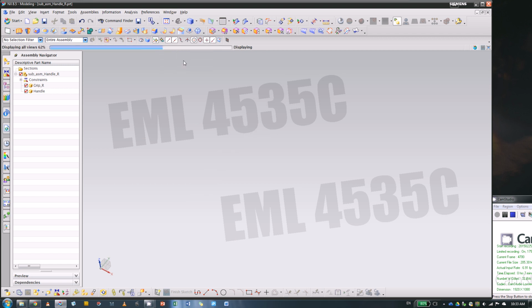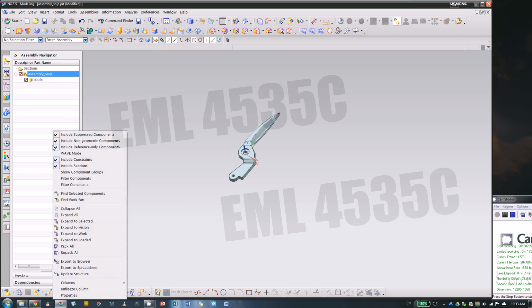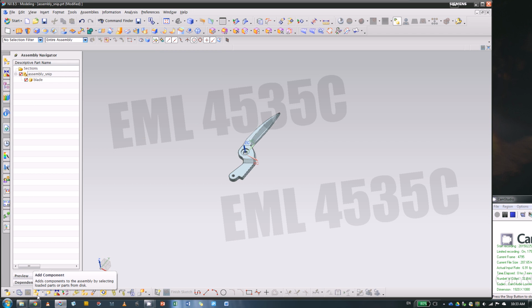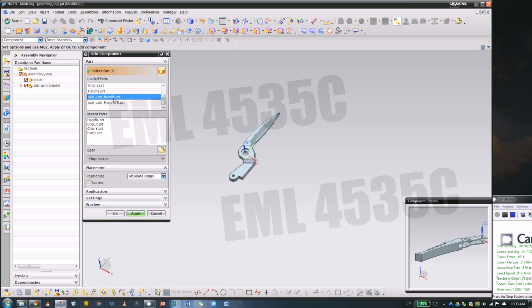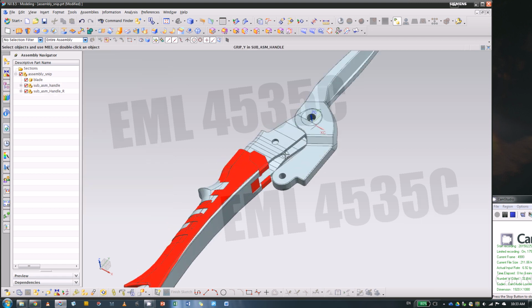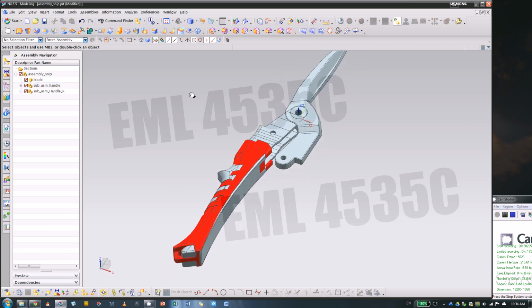So we'll go back to the top assembly. And here you want to add more components. I was trying to find that shortcut. So add components. It's at the bottom. Okay. And we have a couple parts loaded as well as sub-assembly. So I want both of the sub-assemblies, and just say OK. And they do overlap because they were basically built at the same location.